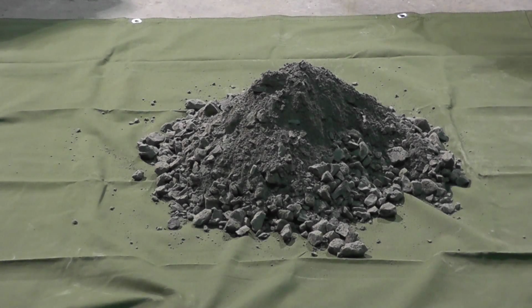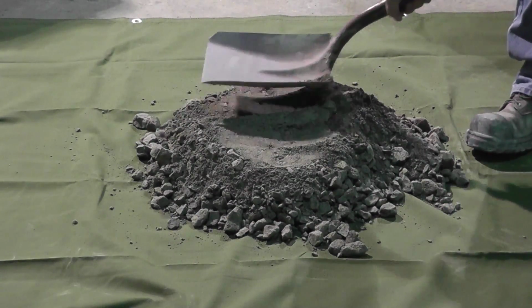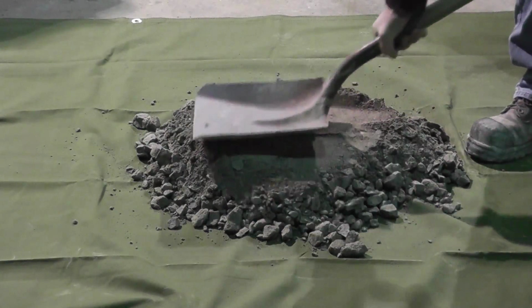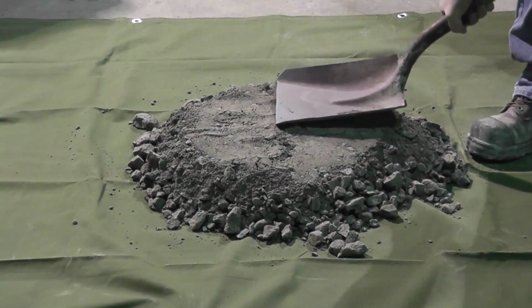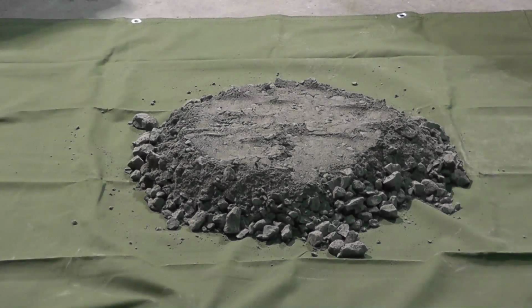Carefully flatten the conical pile to a uniform thickness and diameter by pressing down the apex with the shovel so that each quarter section of the resulting pile will contain the material originally in the pile. The pile diameter should be approximately 4 to 8 times the thickness.